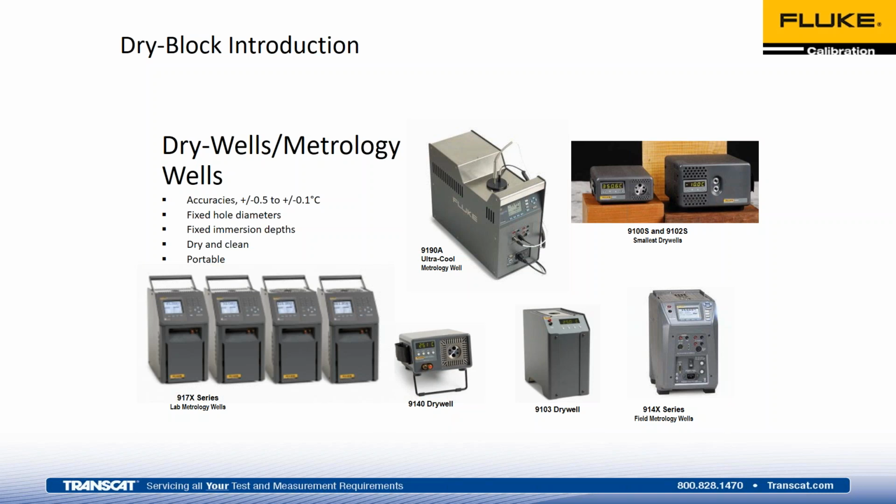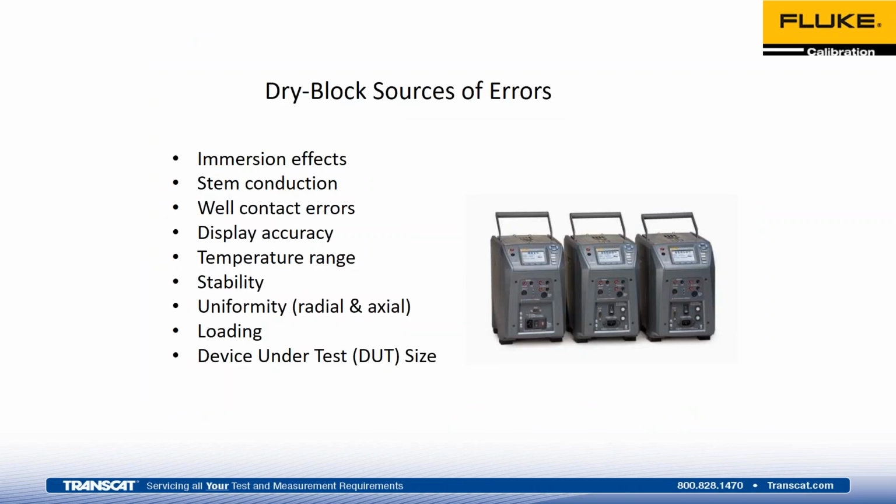Some of the pros of going this route with a heat source is, again, you're not dealing with any fluids like a bath, so they're obviously dry. They're very clean and they're very portable. They also tend to heat and cool a little quicker than a typical bath equivalent. So those are some of the quick pros of a dry well and using them in your process.